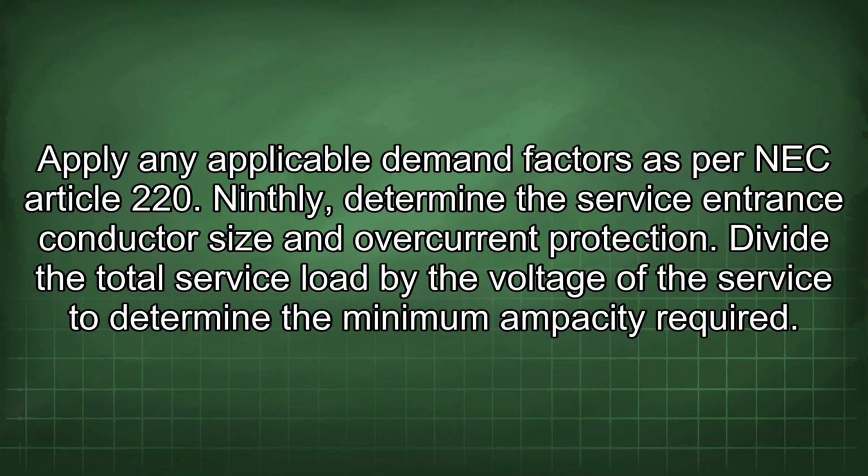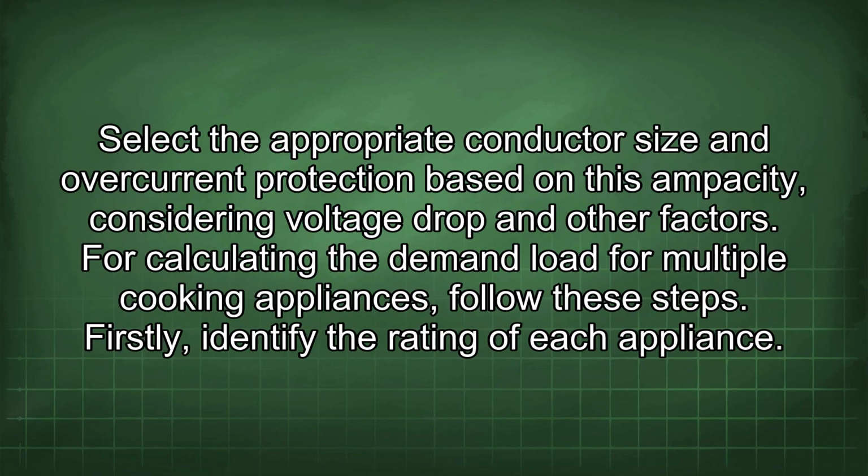Apply any applicable demand factors as per NEC Article 220. Ninthly, determine the service entrance conductor size and overcurrent protection. Divide the total service load by the voltage of the service to determine the minimum ampacity required. Select the appropriate conductor size and overcurrent protection based on this ampacity, considering voltage drop and other factors.